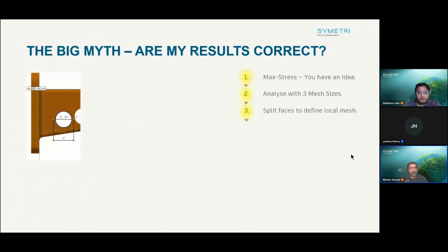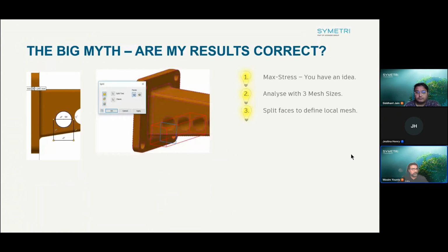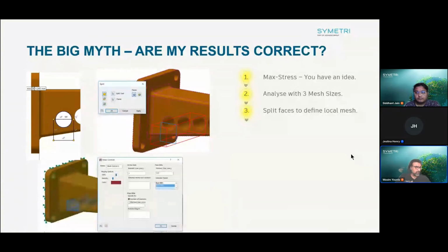Now, split faces is my favorite Inventor feature, where if you have an idea, which we sort of prove to some degree, then I would suggest that you go and split the faces wherever you expect high stresses, using the split face tool commands. And the idea is that it gives you the ability to put a smaller mesh size in there, and by avoiding trying to mesh everything.